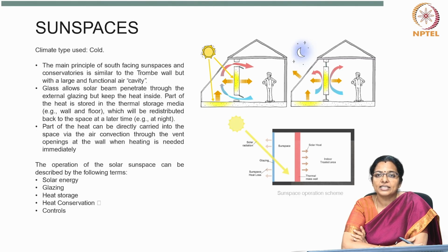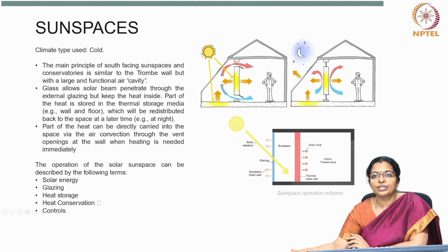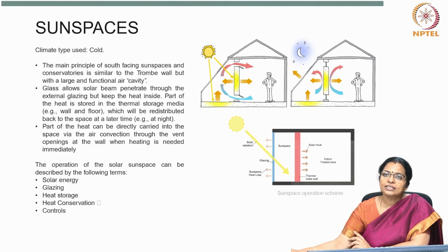Translucency and transparency of the material is another important factor. Translucent material creates diffusion, which means radiation that enters the sun space is scattered and distributed evenly in all the sun space surfaces, avoiding areas of overheating. Some of it also gets reflected and absorbed. So, these two main parameters can affect the reflectance and absorption, and that has to do with the material and